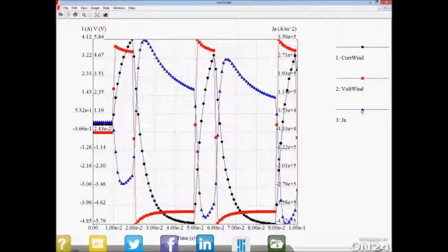Finally, the current at a point in the plate. The current is in response to the time variation. So while the current is changing in the coil is when you're going to see the most current in the plate. So here you'll see that the peak actually corresponds to a point like this. When the current is turned on, the current in the plate goes down, reaches a peak, and then starts to decay back to 0, because as the current in the coil becomes steady, the current in the plate becomes 0. There are no eddy currents due to a steady state current.